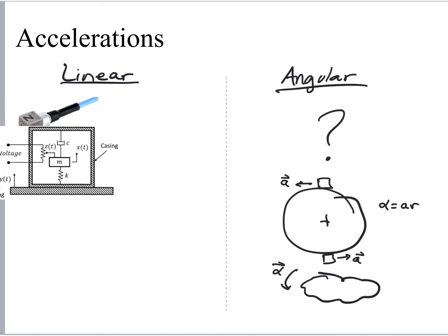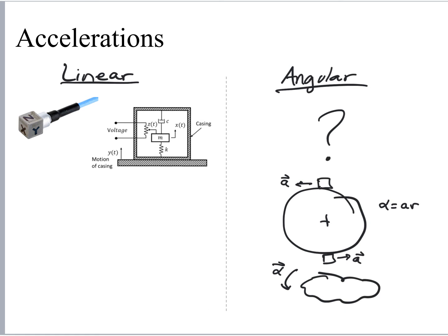And the way that these accelerometers work is by using a suspended mass. That suspended mass, right here in this diagram, is attached to a casing, an outer casing, by means of some sort of spring and damper system, so that the mass is free to move, but within a certain range of motion and with certain predictable dynamics. An acceleration of the motion of the casing causes it to move relative to the mass, which actually serves as the inertial or stationary reference point.